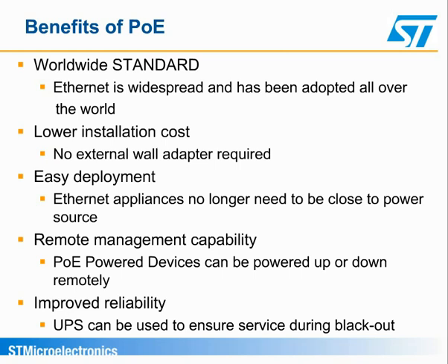PoE lowers the installation costs because the terminal does not require an external wall adapter. It eases the deployment of such appliances since they no longer need to be close to the power source. This is specifically applicable to, for example, wireless LAN access points which had to be placed on the roof or on the ceiling. These terminals will be reached by only one cable, the Ethernet one, and not an Ethernet cable plus the power supply.